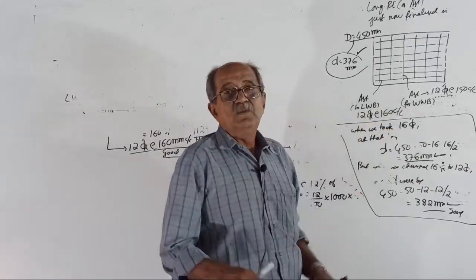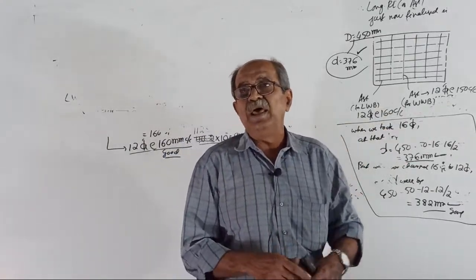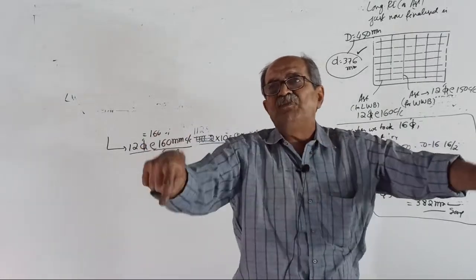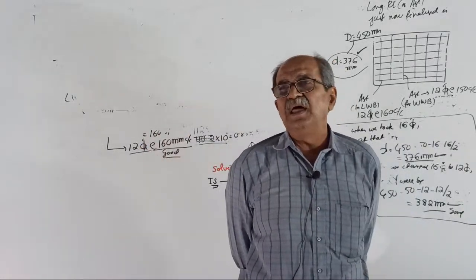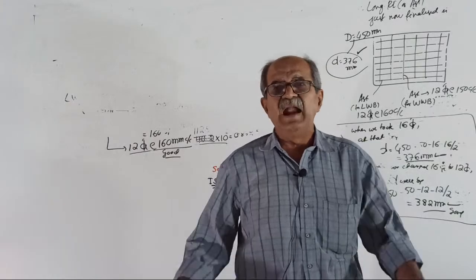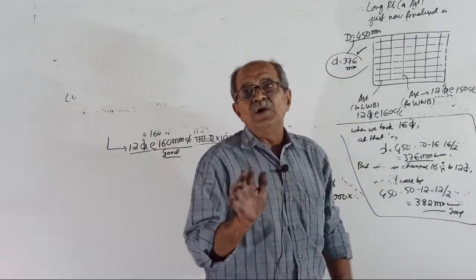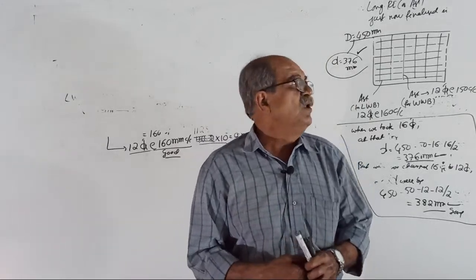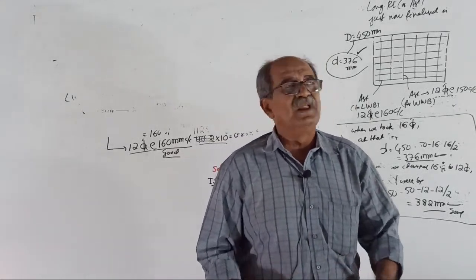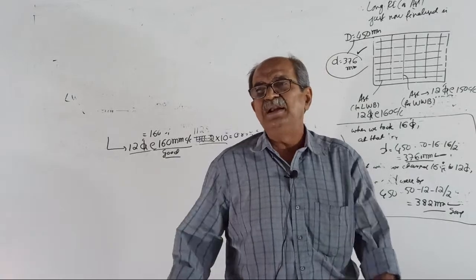Now, when you design the footing by software, length and width you have to fix. So many people decide by experience. Okay, leave that now. Then, you need not perform the pressure calculation, lengthwise projection, widthwise projection, bending moment, nothing.